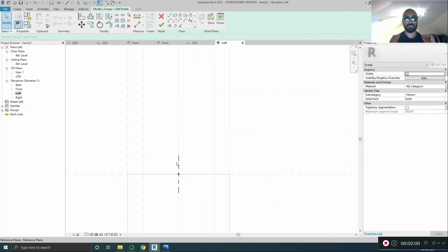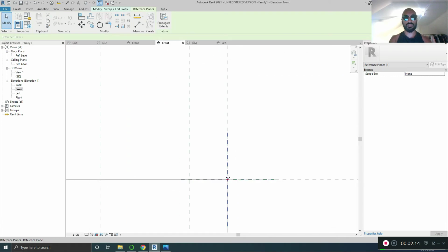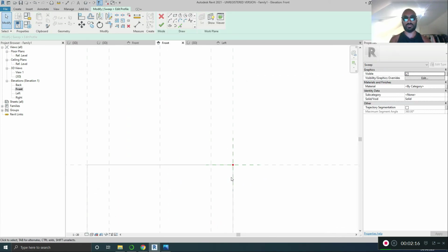If you can only select this reference plane and not the one over here, then go to the opposite. So if you're on front and you can't see it, and you can only see this one, then go to left or right. So for me, it's front. On front, I can see it. It doesn't really matter which way, as long as you can see both reference planes. That's the only one you can draw on. Anyway, so now I want...